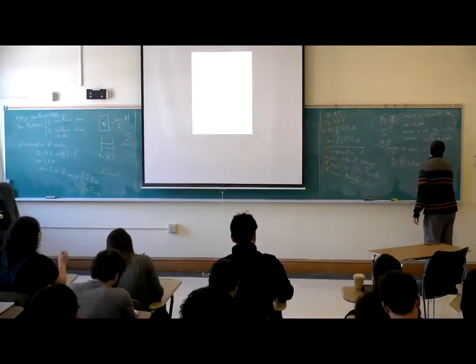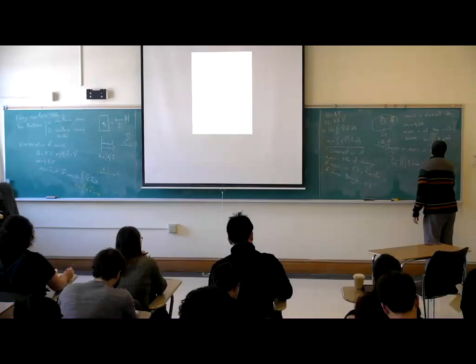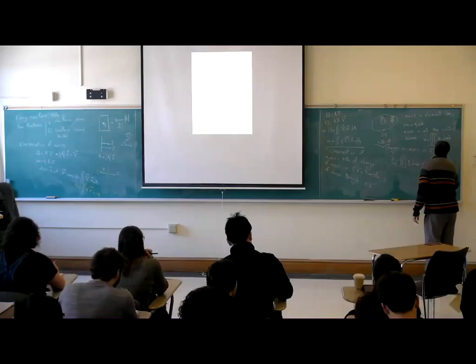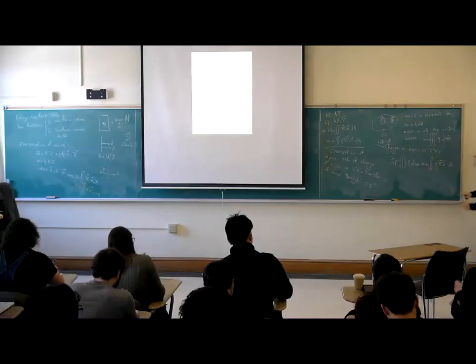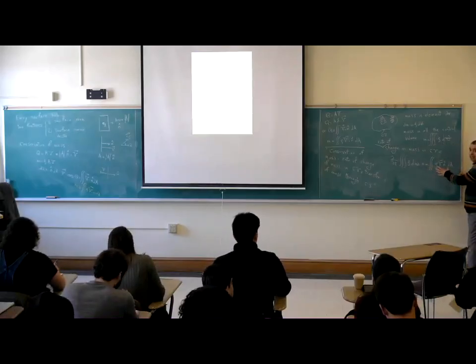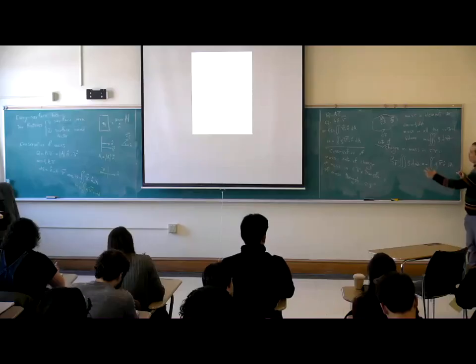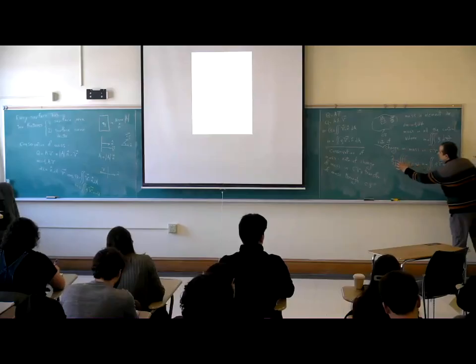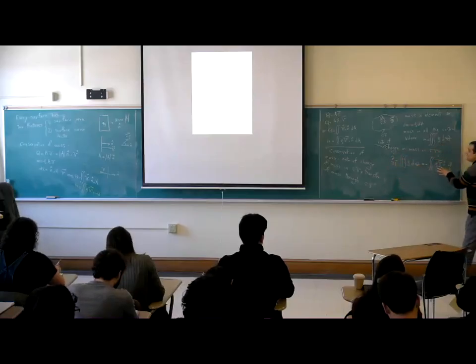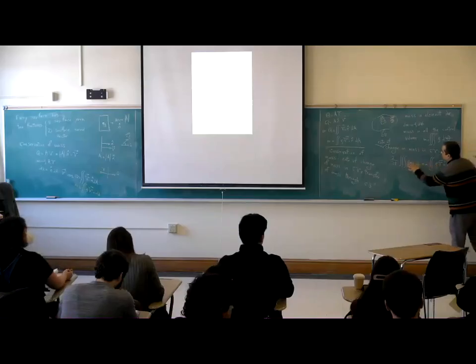Negative rho V dot N dA. Why should I put a negative? Because if mass positively goes out, mass inside goes down. If this is positive, this should drop. If this is negative, it means it is coming in. Negative by negative, positive, this goes up.